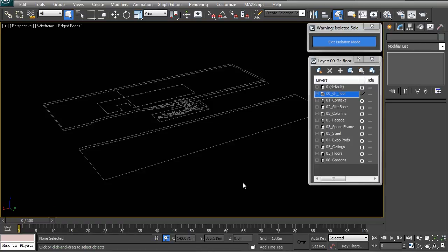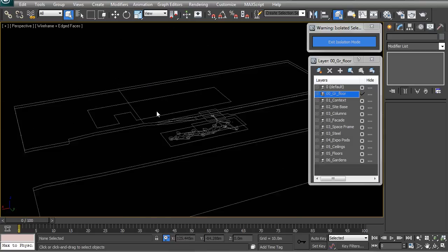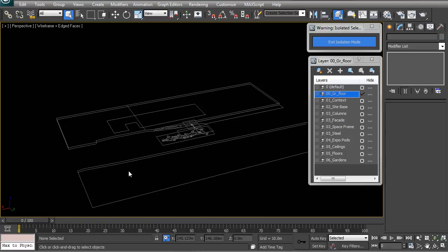2000 is fine. And then in the next lesson, we're going to open up AutoCAD, and we're going to have a look at what we can do with all of that exported geometry. So that's the end of this lesson. What we've basically covered, just to recap in the last two lessons, is the process of extracting out shapes and splines out of polys or meshes or any other 3D object by using the create shape command or tool. And we've also looked at using the section tool so that we can cut through an object and extract the shape out of what is being cut through. So once you get a handle of all of that, we can now jump into AutoCAD and we can start to organize that ground floor plan.